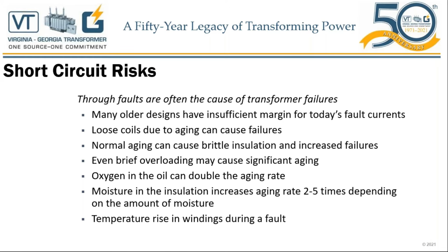Because if the core and coil is not anchored correctly within the tank itself, by the time it gets to you all, to our customers, then the active part, the windings, the leads might have already shifted. Remember, the mechanical forces due to short circuits is not just within the windings. That is the worst case scenario, of course, but the leads.